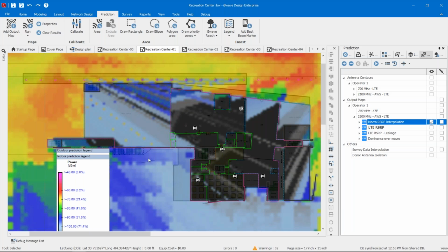So that looks much more pessimistic compared to what we saw with that only 10 dB default loss that was imported. And so we see the impact of these concrete columns and the shadowing effect from those inside the building, as well as the refraction of the signal coming in.